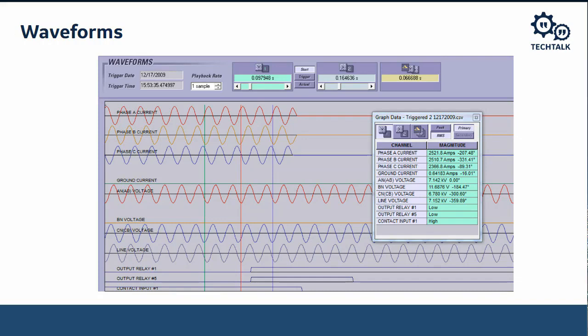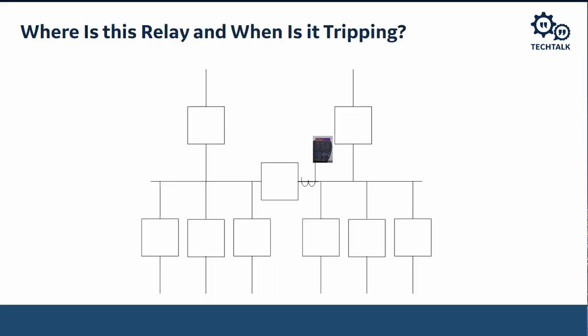So the next question that I had to ask was, well, where is this breaker at? What is this breaker doing? And this breaker is a tie breaker in a main tie main arrangement like this. So I'm showing that 750 sitting there on the tie breaker. So the two mains are on either side of it, and they're feeding from the top, and then there's multiple breakers that are feeding the switchgear. The switchgear is feeding the plant auxiliaries, so pumps and things like that.